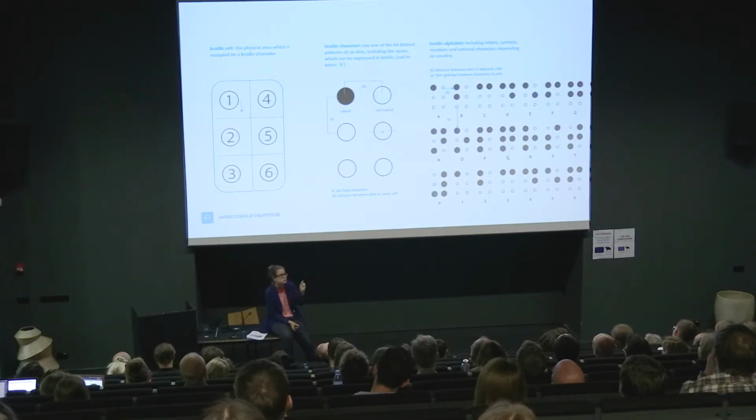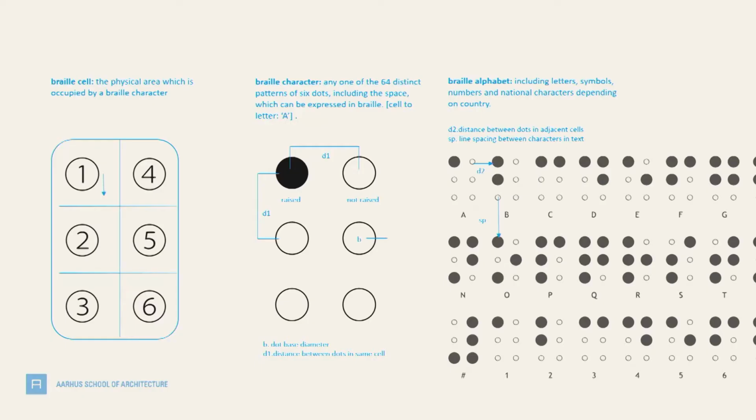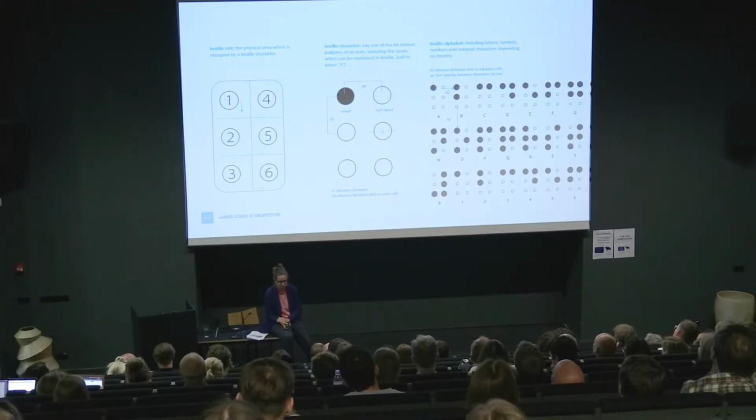But not only that, but the Braille code also entails how it's computed and how it's fabricated. So there's particular dimensioning and sizing from each individual cell or pixel in that part, which should be raised about 1.2 millimeters. The distances between different points in the cell, and then the distances of spacing both between different words, as a break between different words and as a break between lines of words, so that the full text is actually developed. So that's another one of the base components.